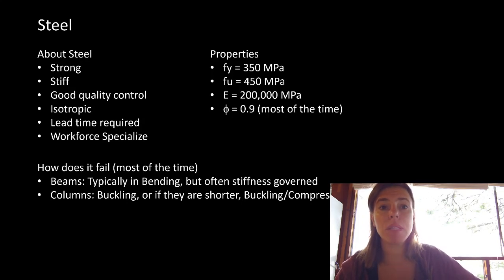And the relationship between stiffness and strength is not linear. As you remember, when we were looking at a uniformly distributed load on a simply supported beam, strength was governed by depth and length, but stiffness was also governed by depth and length, to the power of 4 versus strength, which would be to the power of 2 for different elements within it. So taking away material for stiffness has a much bigger impact than it might for strength.